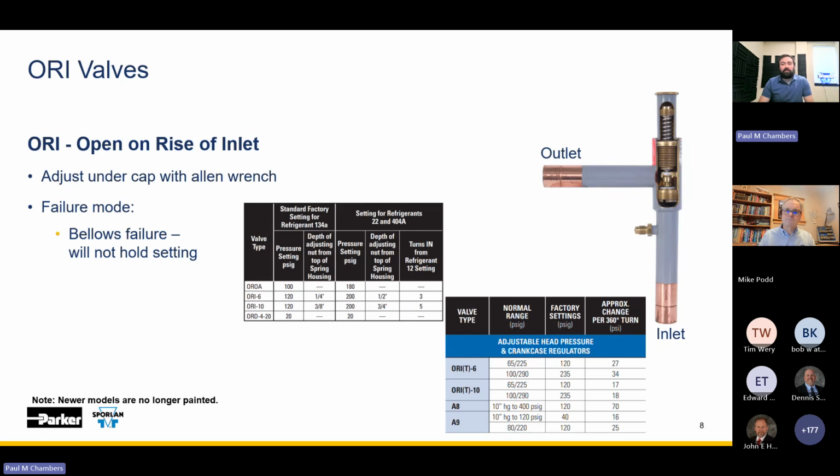Okay. That's really clever. Actually, I had thought of trying to do that before, because that is the difficulty, right? You install this valve, it's summertime, you want to make sure it's set, but it's wide open. But you also want to make sure that you're not getting another call back in the winter because your condenser's not functioning properly, your cases aren't feeding. So either a calculated setting, or like you said, going to where it starts to shut down, and then once again, a calculated setting off of that point. Calculated off factory or calculated off of starting to close.